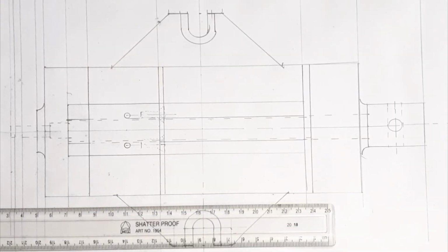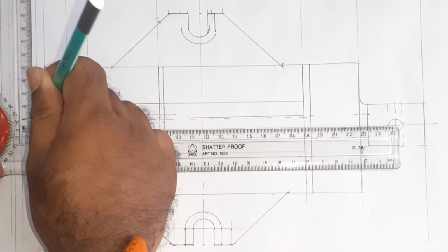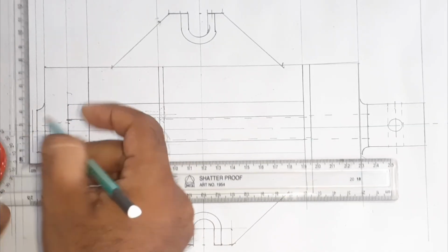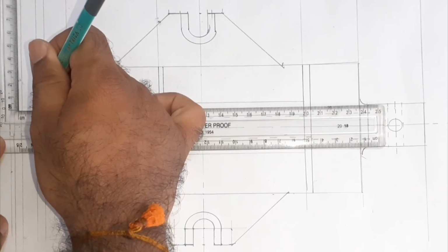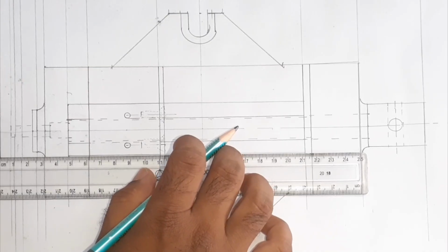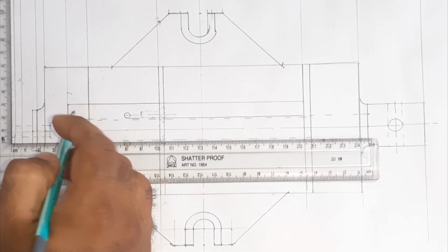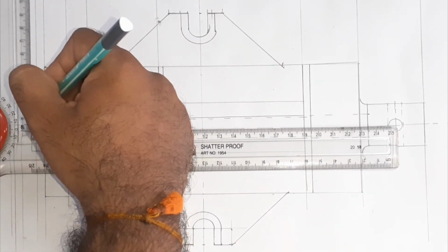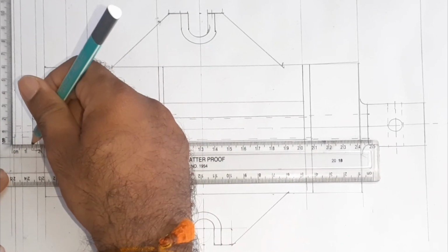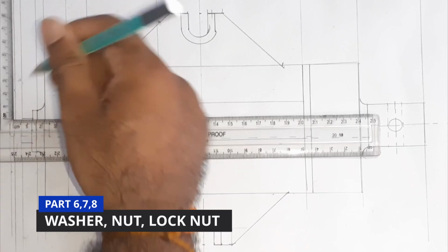Okay. So here you can see. So let's mark first the washer length, that is 3 mm here, and also the diameter we know that is 32 mm. So the next step is the part number 7 and 8, that is nut and lock nut. So the nut and lock nut will have the diameters, as I said, of 20 mm. So 20 is, we have to mark 10 mm on both the sides. So let's mark this 10 mm on both the sides and then join to the next projection lines that we have drawn from the front view.